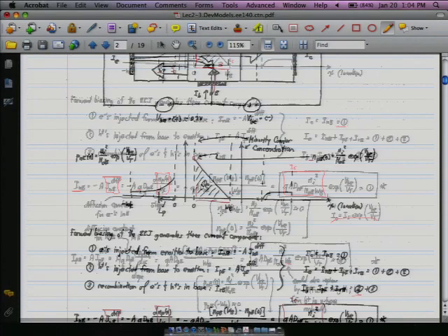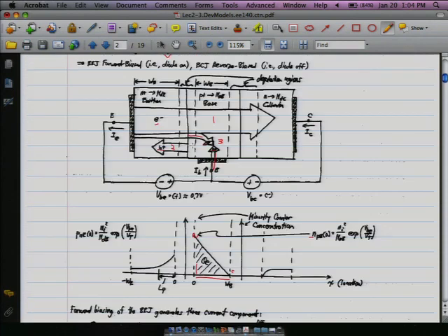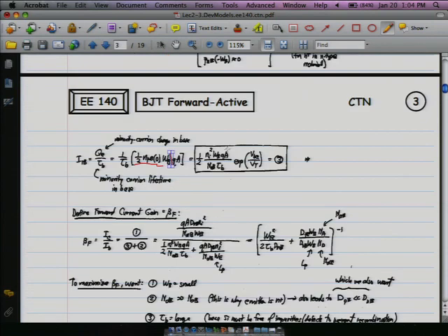The base current is these last two factors that we talked about. It's both the holes flowing here from the base, and the electrons flowing in the opposite direction right here. Those two sum, and you get the base current. All right, so that at this point is the worst of the math. From here, we can start using a little more intuition to figure out what's going on.